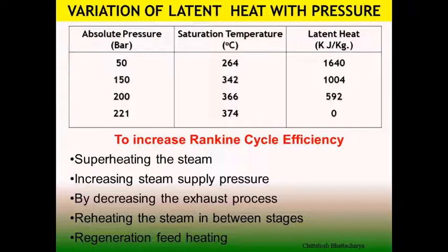264 degrees centigrade, and latent heat of vaporization requirement is 1640 kilojoule per kg, and if we go on increasing the pressure to 200 bar, then saturation temperature comes to 366 degrees centigrade, and latent heat of vaporization that is required reduces to 592 kilojoule per kg.